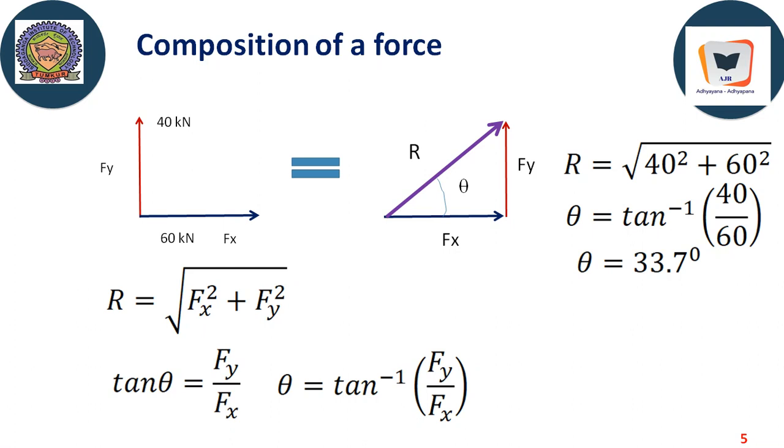What we have to do is calculate the horizontal components of all the forces, compute the vertical components of all the forces, and take an algebraic sum. When we take an algebraic sum, we are mindful about whether the force is positive or negative. In an arithmetic sum, regardless of the sign, we just add, and this we should not do.